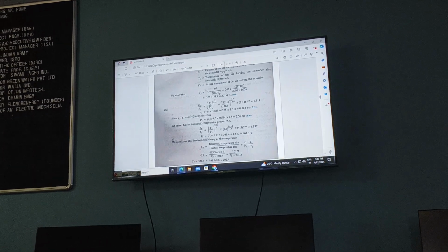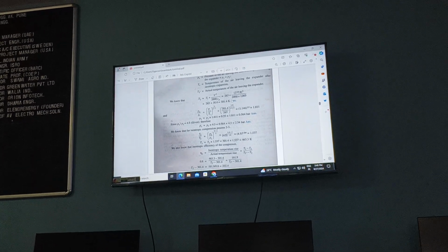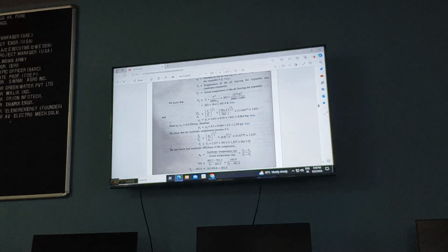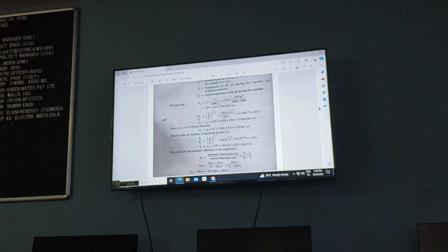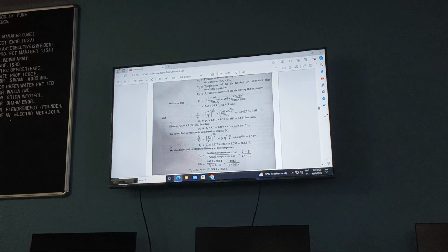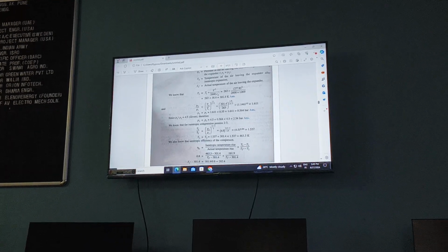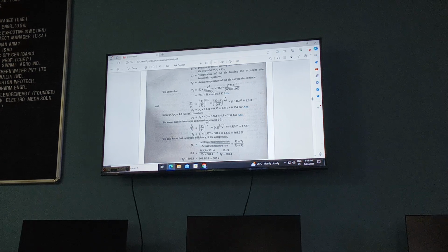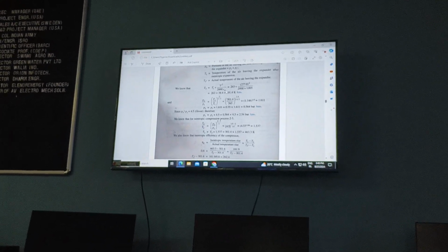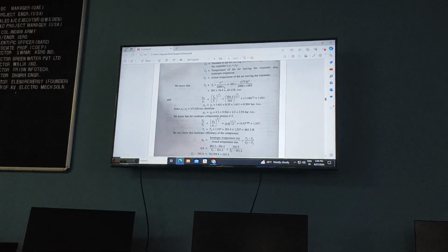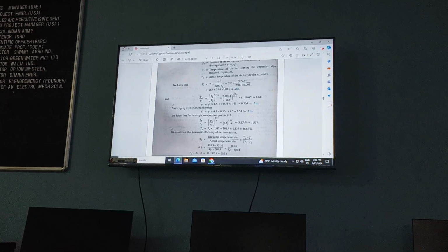Here a little extra twist to this formula is used. The formula that was in the initial derivation, they have used here. Okay, how? Actually here, now the ramming process. From ambient to ramming, why is pressure increased? Because the aeroplane is running at high speed, so the kinetic energy of air is converted into pressure energy.